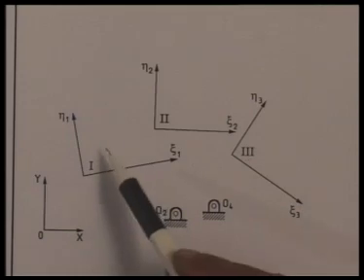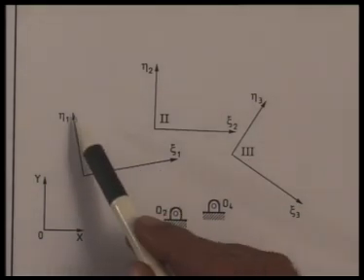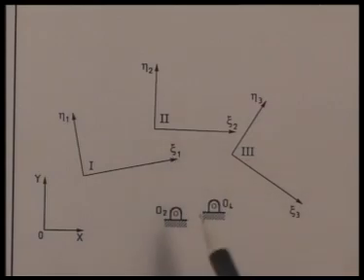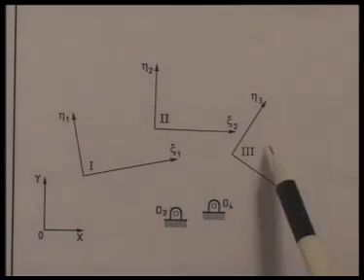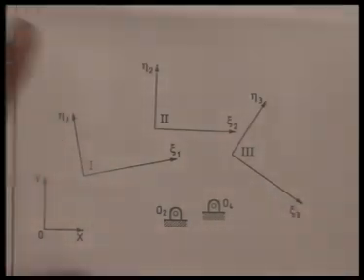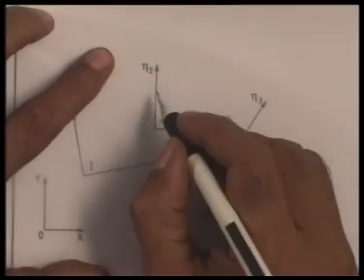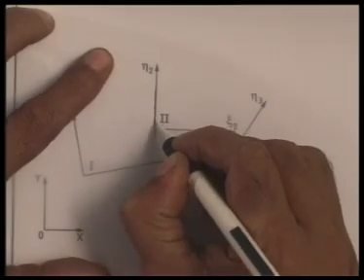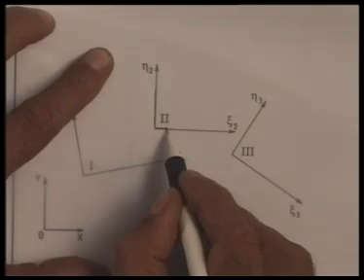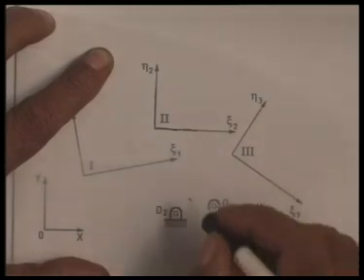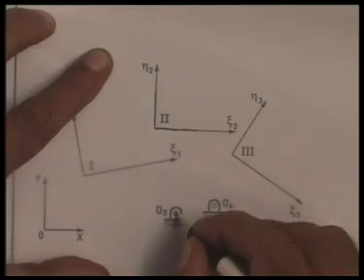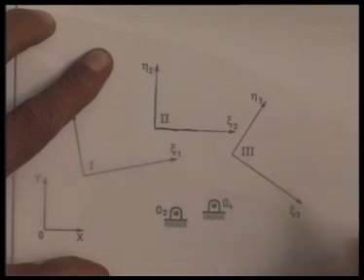To locate A1, B1, we fix the coupler at this first position and let O2, O4 move, keeping the same relative movement as prescribed here. So let me do this inversion by using a tracing paper. I put the tracing paper here and draw this eta 2, zeta 2, and the position of O2 and O4 I mark on this tracing paper.